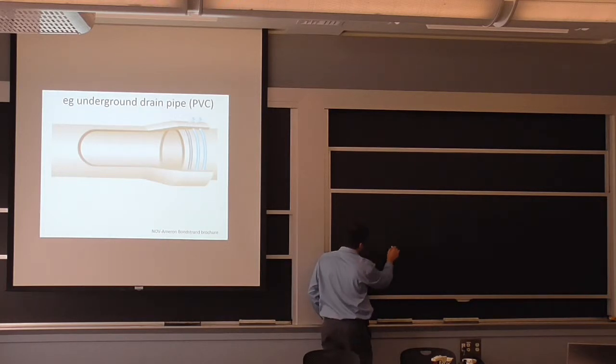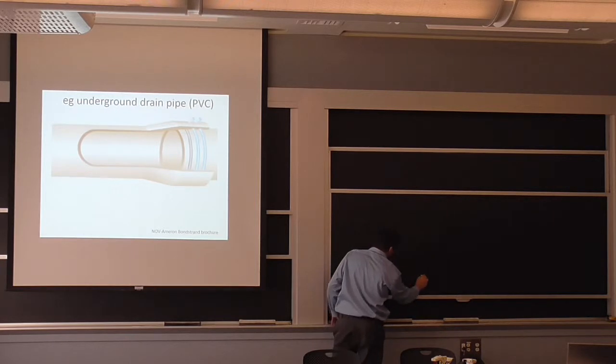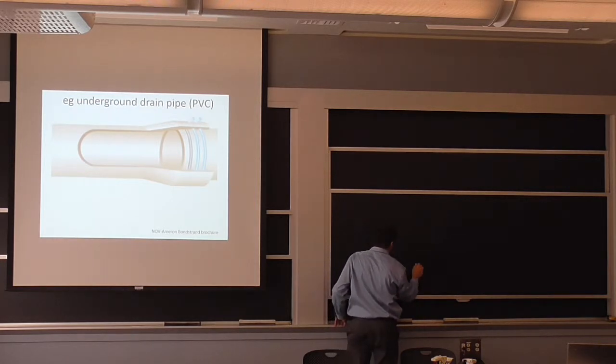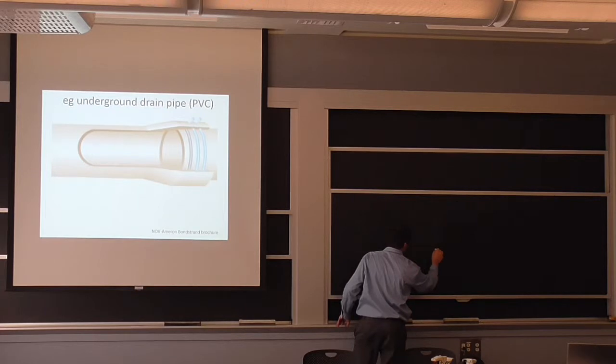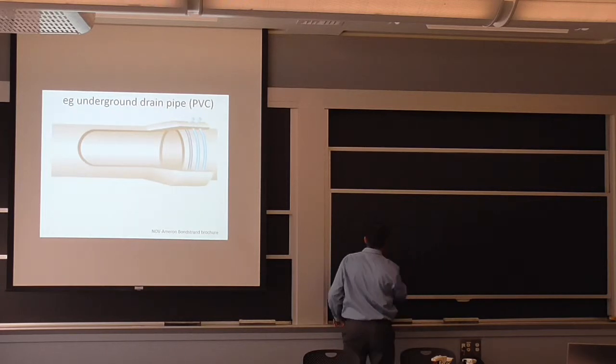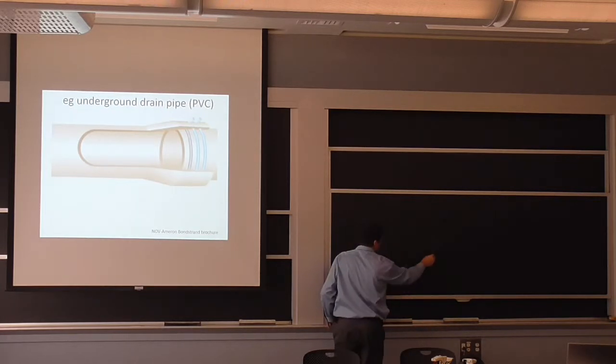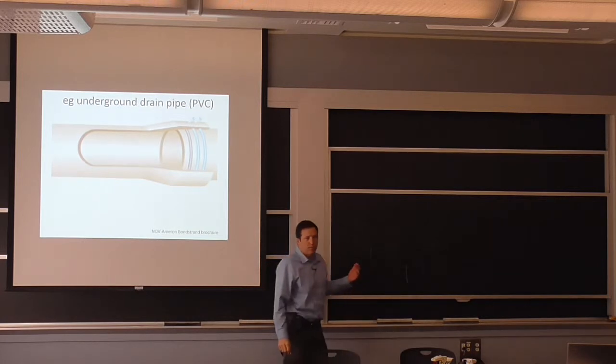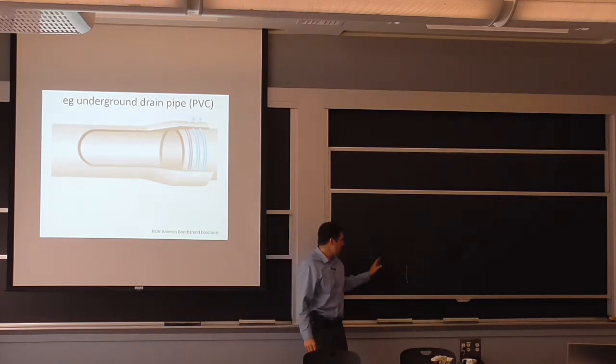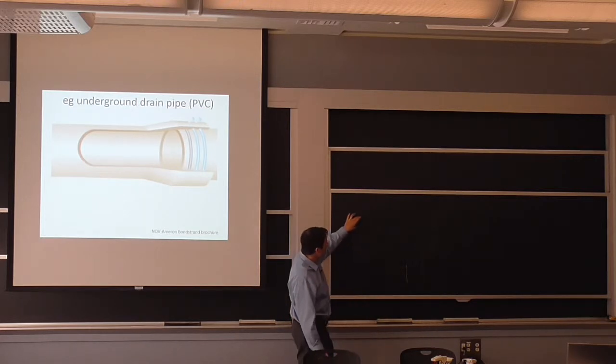You can make your main on purpose, you can say I'm going to make it in 2 segments or 3 segments, so you introduce a loop in it, and you fix it, say I fix it here, I fix it there, I fix it there. Now all of a sudden I only have 1 inch total, because it's not going to move at these 3 locations and allow for having these short laterals.